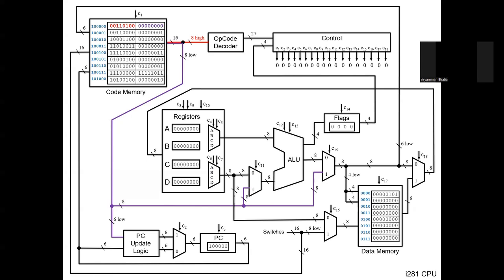And using C12 and C13, we direct the ALU to show us the comparator circuit. So using this, basically we are comparing values in, say, register A and register C. So we would set C4 and C5 to 0, 0, and C6 and C7 to 1, 0 if we wanted to compare the values in register A and B.